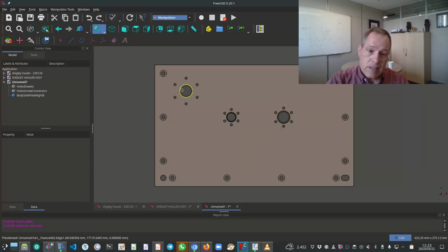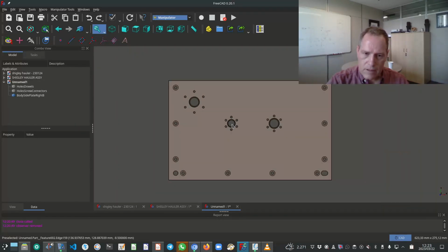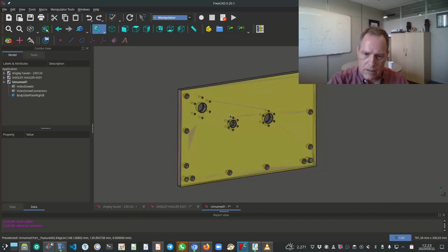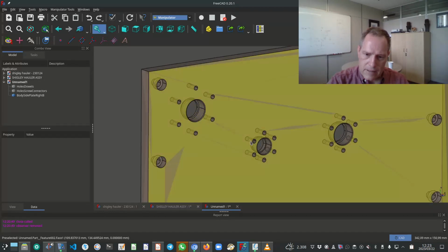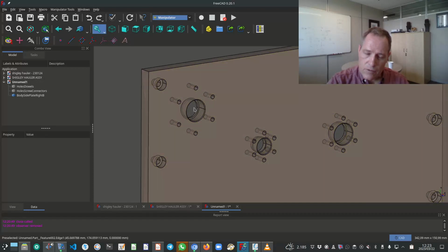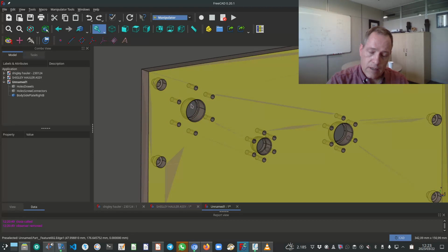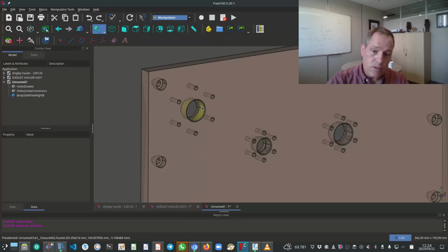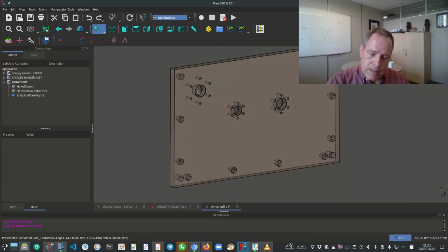So the positions of these bearing diameters, if I can just rotate it a little bit, so there you can see, I'm talking about that face, and that face. I think for practicum 4, you're only specifying the location of one of these holes, because the other two are basically the same, just different dimensions, but the dimensioning strategy is exactly the same. So we will specify a basic dimension from the secondary datum, from the primary datum, and we have the position of that hole.